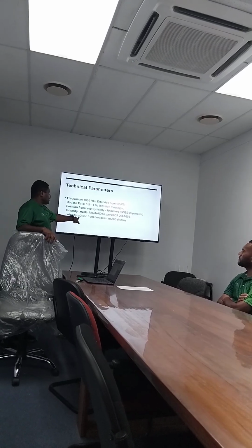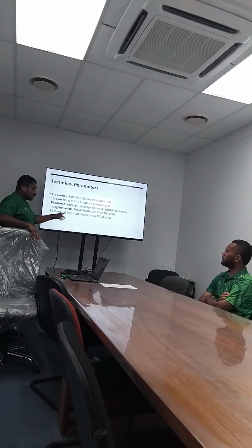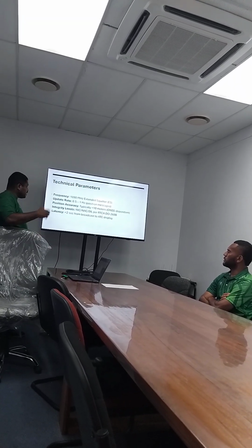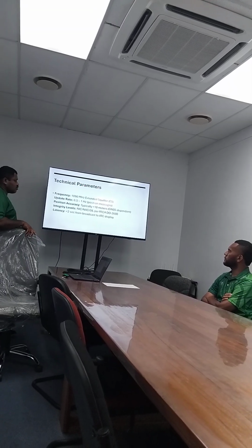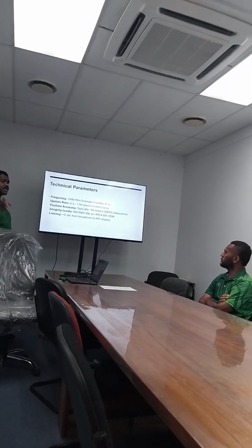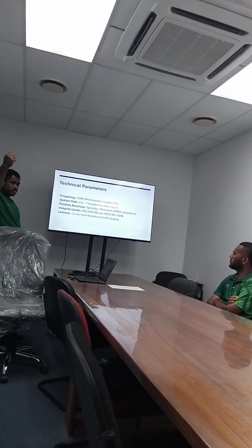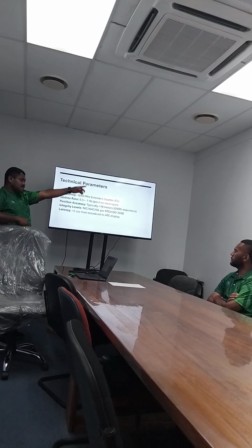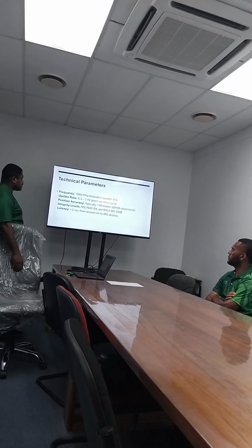Latency of a received message from the ground station being sent to the air traffic controller display should be less than 2 seconds, not more. So remember, if an aircraft is coming to Honolulu, and the station is receiving it, before we count 1 to 2 seconds, the controller will be seeing it at Nandi. That's how fast it has to be.